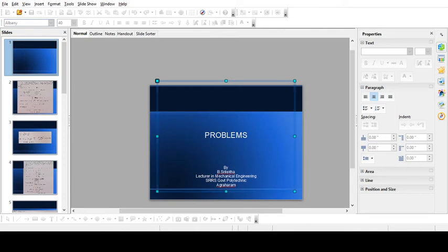So now first, the stress given in the x-axis is 50 Newton per mm square. Now the stress in the y-axis is minus 80 Newton per mm square because it is a compressive one and it is acting in the negative direction. So now strain in the x-axis is Ex equal to sigma x by E minus sigma y by mE. So this is due to the effect of the compressive force.